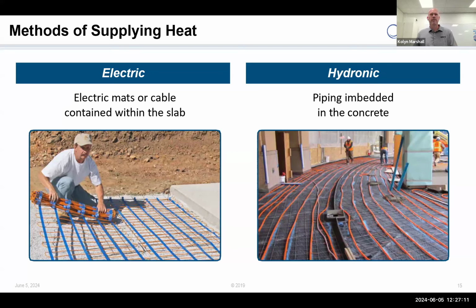Normally, you can go as big as you want with a hydronic system because we just up the boiler size, right? We have a little bit more design flexibility on that. Conversely, though, electric systems have a greater advantage on small areas. Boilers, mechanical room setups, the added fluid with the glycol. The biggest cost of a hydronic system is the mechanical room. The boiler, the pumps, the expansion tanks, all those things are the bulk of the cost.